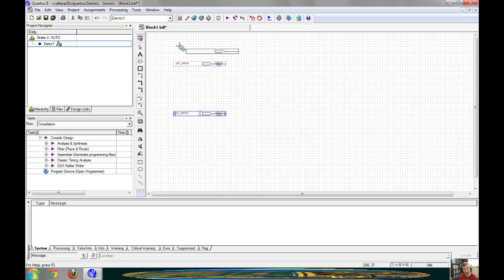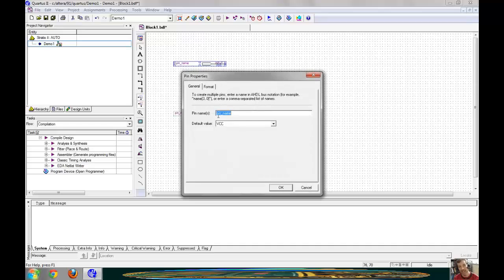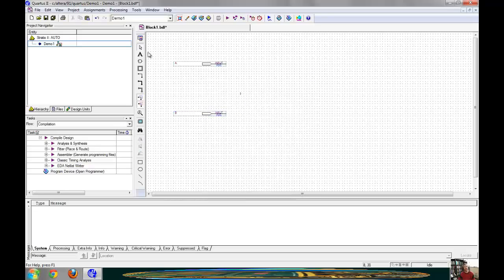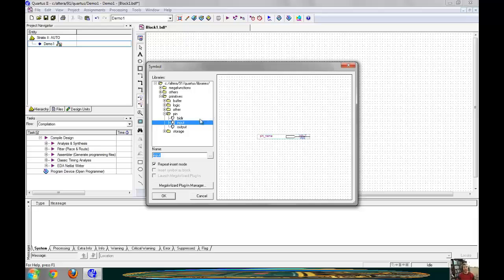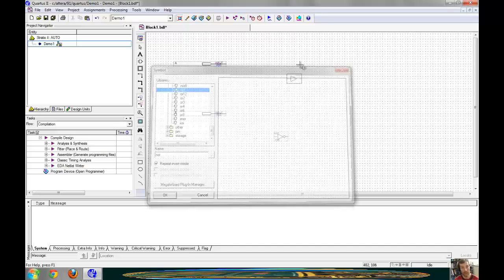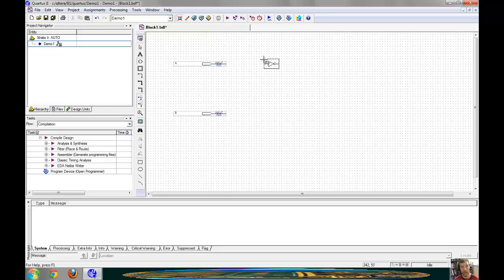Suppose I could tell you that the function I am intending to draw right now is an XOR function. So I'm going to take A and B and I'm going to create their XOR. If I go back to here now, we have inputs. Now I want some logic. Well, to create an XOR, the first thing I'm going to have to do is invert both of the inputs because I need both of the inputs and their prime to create the XOR function.